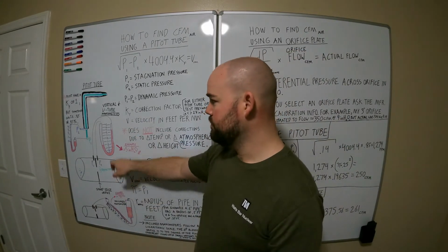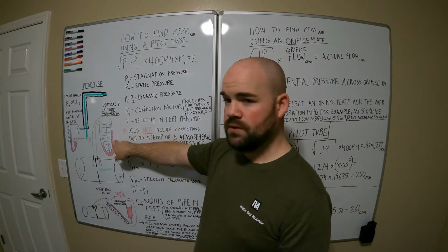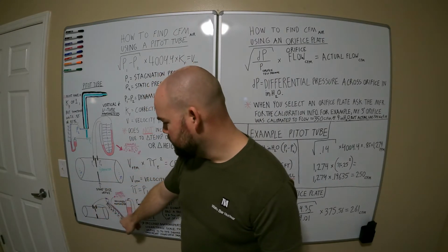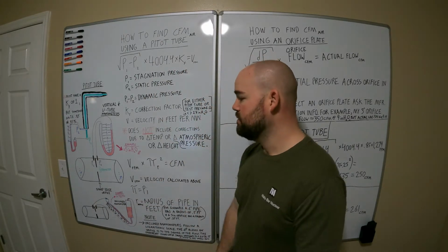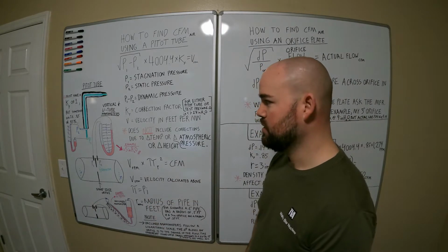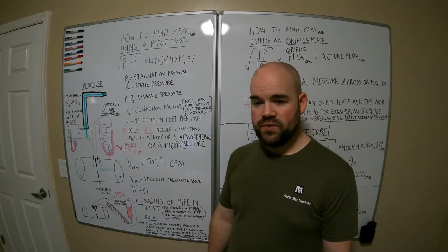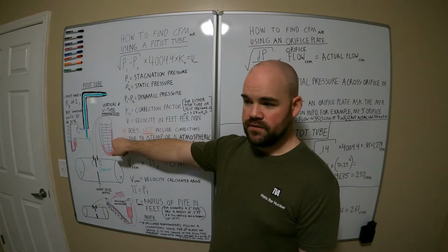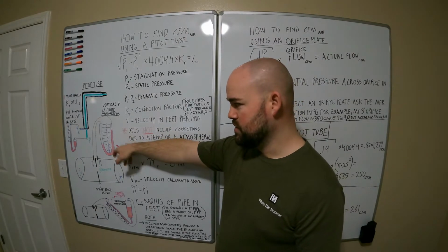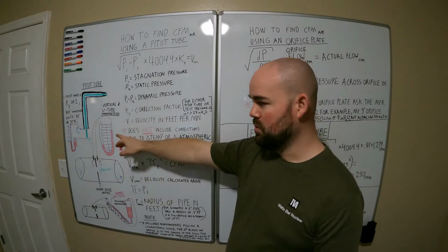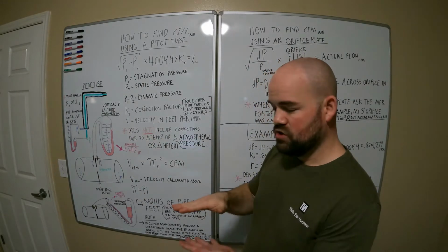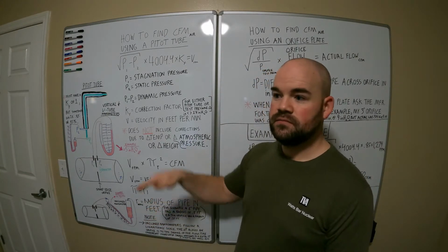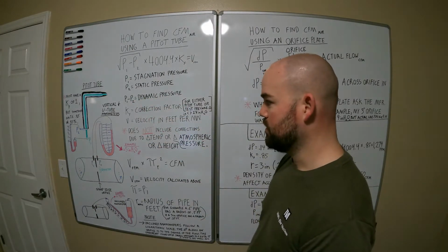And what you're going to do is one of these things. Well, there's actually three. You have a vertical U-tube manometer, you have a standard well type manometer, and you have an incline manometer. There are differences, and scales change a little bit depending on which one you're using. If you use the 0.82 something specific gravity red gauge oil, remember you have to take into account there's roughly a 20% or 10% increase in your scale length. I don't remember the math exactly, but you can look at that, and you just stretch your scale accordingly. That's because it weighs less than water, so it takes a longer distance to reach 1 inch of water.